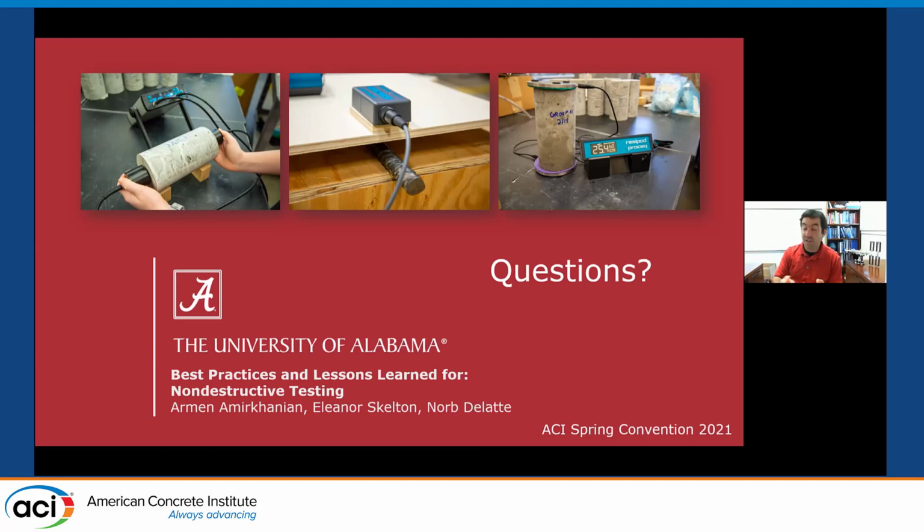Forgot exactly what those are called. And that will sometimes throw off the cover meter, especially if it's densely reinforced and they used a lot of tie to get it all there. So I have done it. The students got a little frustrated because they couldn't make sense of the data. But then they confirmed what was there with GPR, and that really helped a lot more.